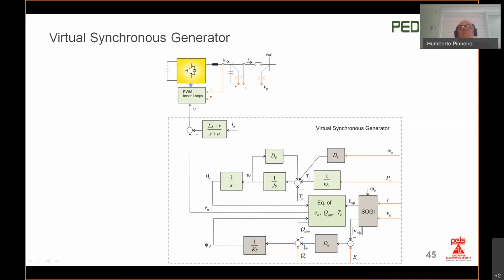So basically, we see this part over here that is associated with the swing equation. We have this additional feed-forward compensation for this damping that changed the operating point. So when we want to have an operating point at the frequency omega 0, we added this additional component to the summation of these torques.